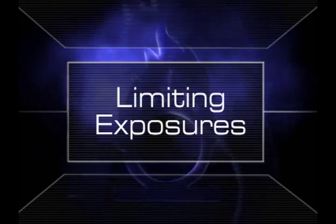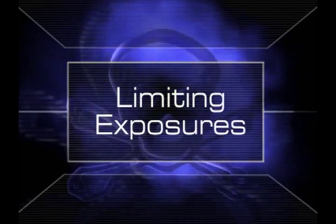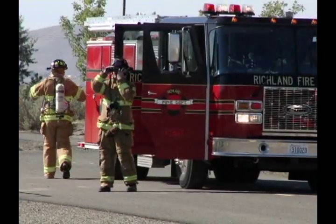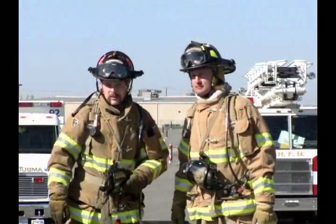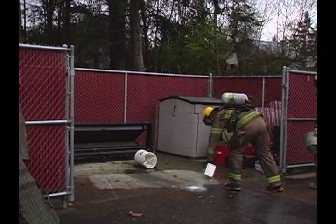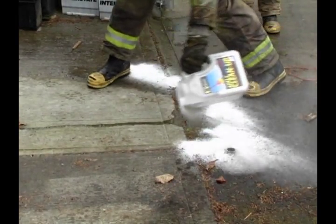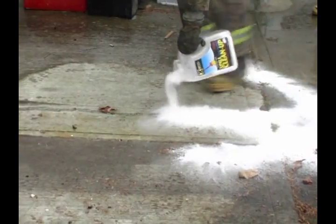When you work the scene of a hazmat incident, one of your primary goals should be to limit exposures. Knowing what your available resources are and how to maximize them will help you achieve this objective. If you are dealing with a very small amount of a known material, such as a fuel spill, you may be able to take offensive measures to quickly control or contain the materials.